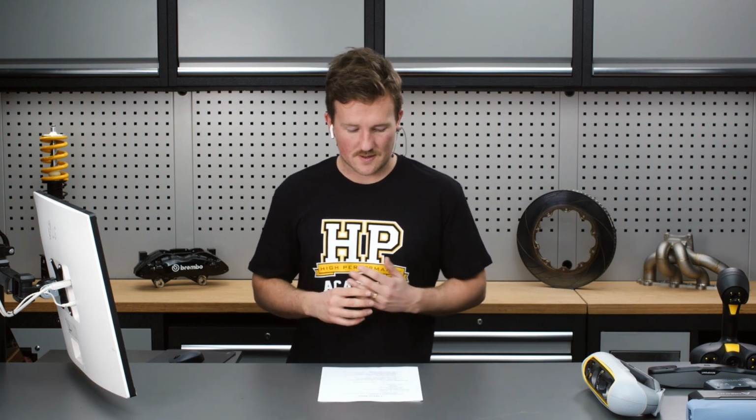It really depends on the application. If you're scanning body panels of a vehicle, for example, you might be able to get away with less accuracy. But if you're scanning something like an engine block or something with threads, where we really want to be accurate, then we might need more resolution and more accuracy, and that's something to keep in mind when we're designing our part as well. If we need to slot holes because we don't really trust the accuracy, then we might need to allow more room for those tolerances.